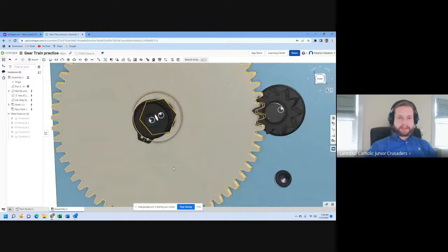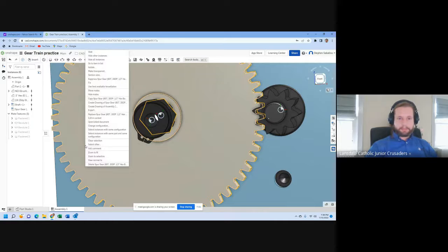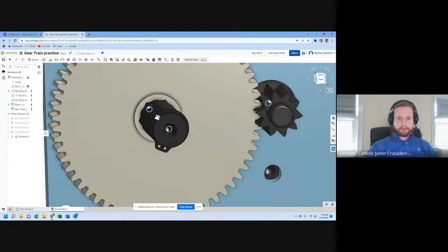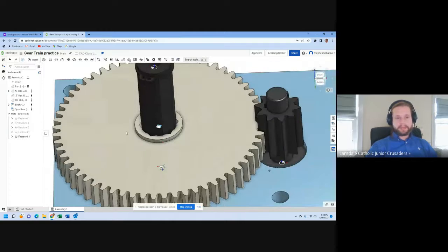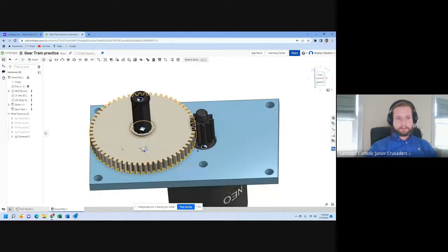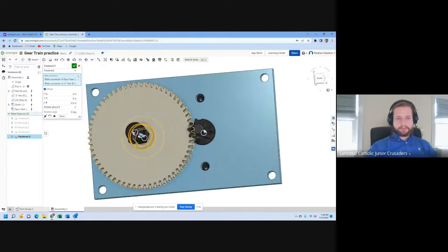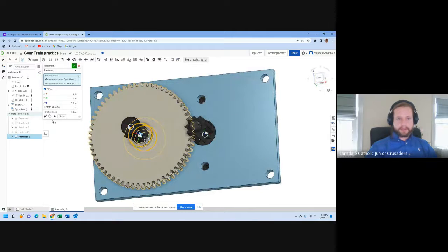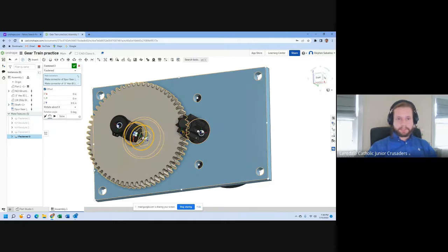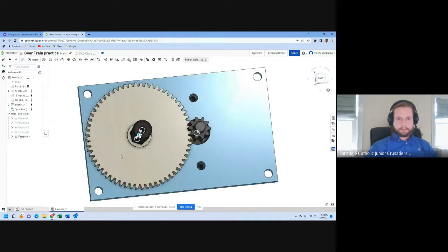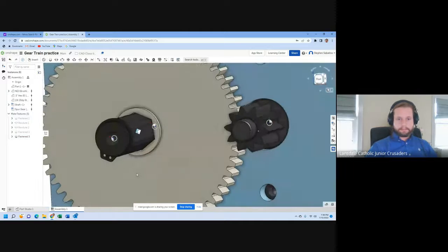You can edit that if you right click on the gear or on that mate there. If you click on the gear, you can hit show mates and it'll show all the mates that are on that gear. And now if you see in the left window pane, it showed that Fasten 3. Right? And if you edit that one. Which this one? Yep. See how it's unhidden? Okay. And then do you see there's a little rotate button at the bottom? It's right next to the flip direction button. Click that once. Yep. Now it should be rotated correctly. There you go. Yeah. Okay.